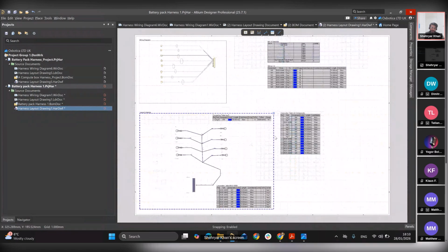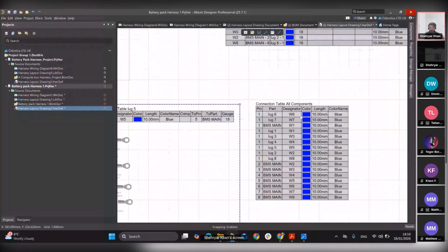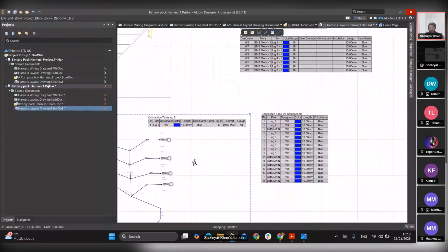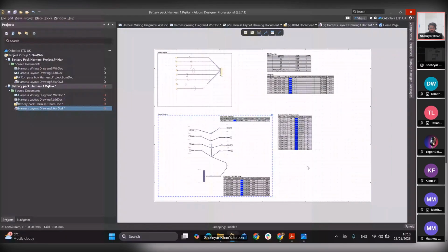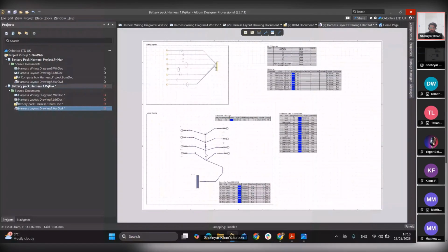And these colors can be defined by you, whatever color. If it's a power or current, it should be red. If it's ground, it should be black. And then similarly, earthing and others should be white or gray. It depends on your standards and characteristics you want to apply to your harness. By having this much data, your manufacturer should be able to manufacture your harness.